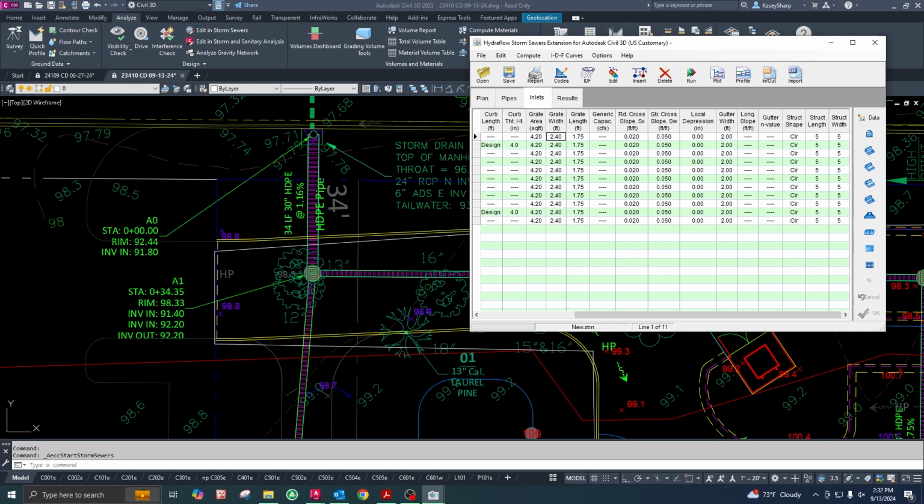Alright. Cross slope's 2%. Gutter cross slope should be 8%. Is gutter cross slope 8%? That's just what we typically spec, correct? Yeah, but this one, we're doing a monolithic curb and the paving right up to it, so just do 2%. Gotcha. And then maybe 1% for the other slope.